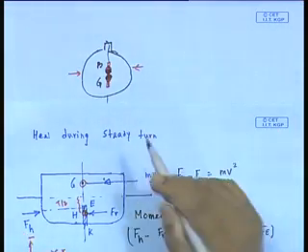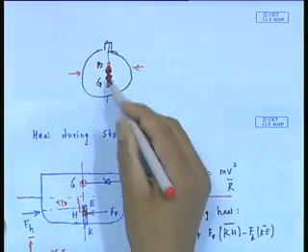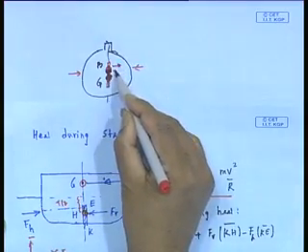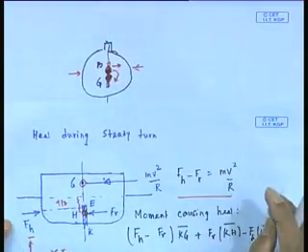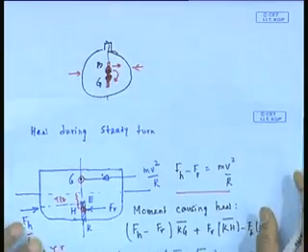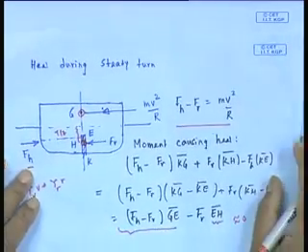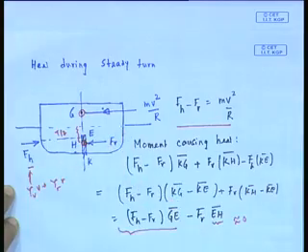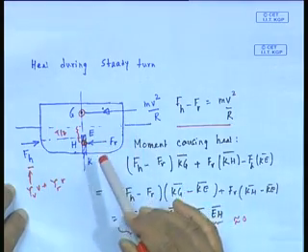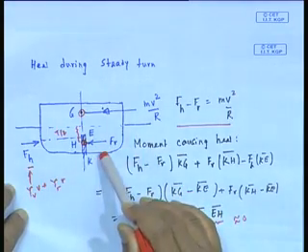So, which side is it supposed to heel? It will obviously heel inwards, right, because the direction has changed now. You know that this moment is going to be like that, while turning inward. More or less, you cannot say for guaranteed, but more or less for a submerged body, usually the heel will be inwards, although it is very approximate, because to find out the heel you have to find out all kinds of interplay of the hull forces, which is not small.